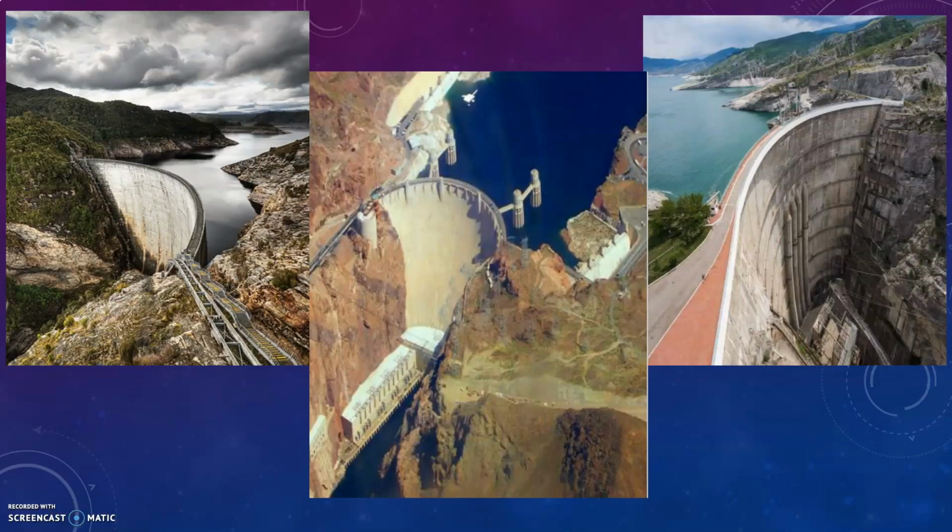The advantages of arch dams include: arch dams are particularly adapted to the gorges where the length is small in proportion to the height. For a given height, the section of an arch dam is much smaller than a corresponding gravity dam. Hence, an arch dam requires less material and is therefore cheaper.